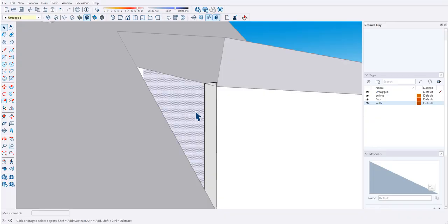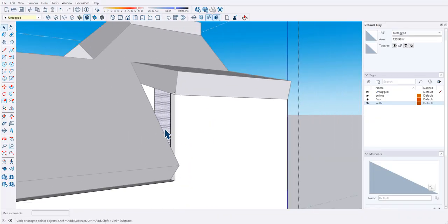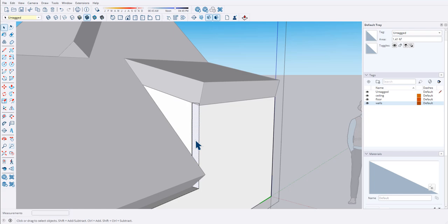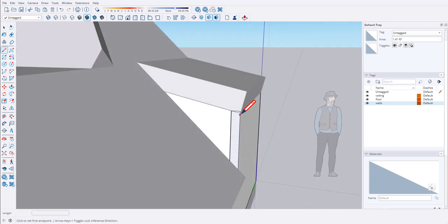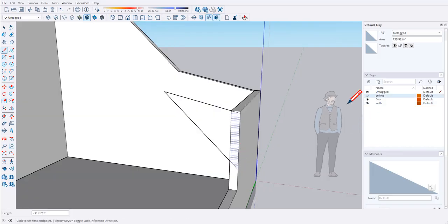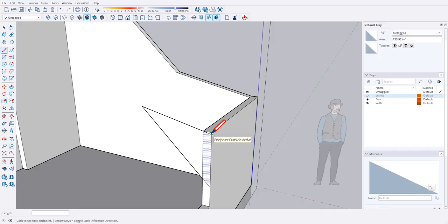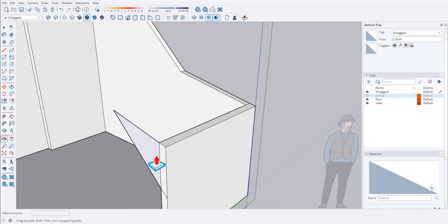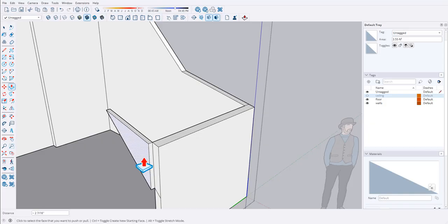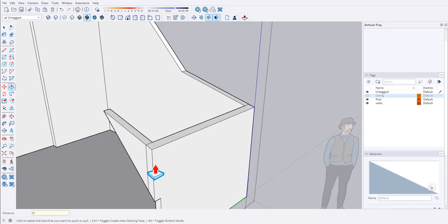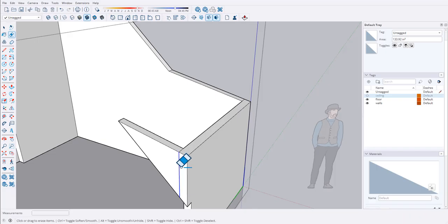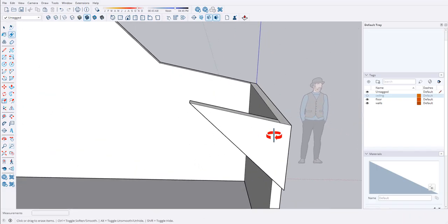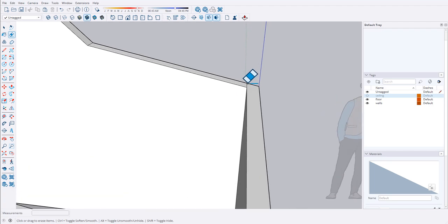So this is a hole. I'm in the wall component now. I'm going to draw a line from here to there to there. Now I'm going to the ceiling, make it not visible. Okay, P for push pull. P for push pull all the way across. And then I'm going to do this way, let's say 4 inches. Erase. And then that can be erased because I push pulled that across.